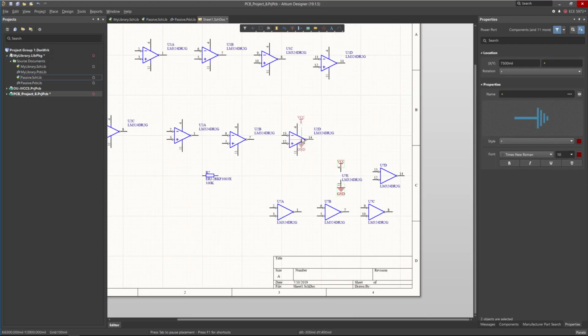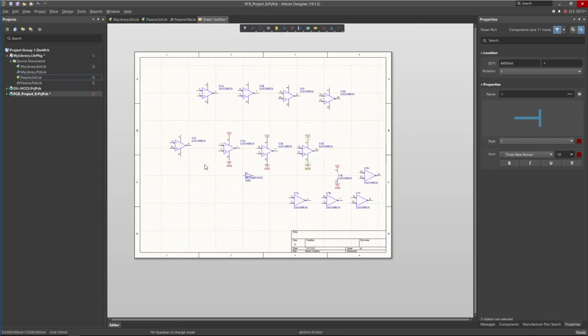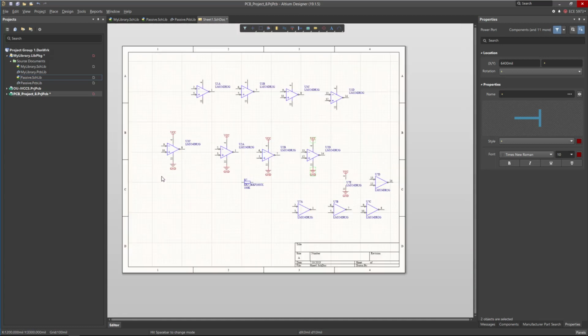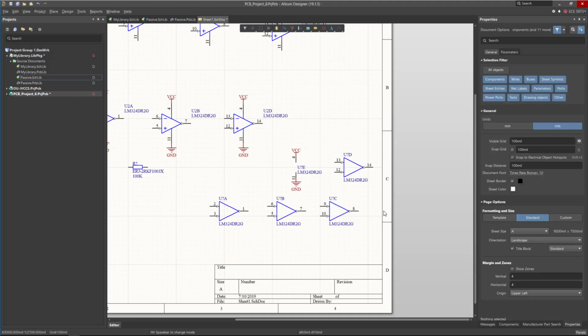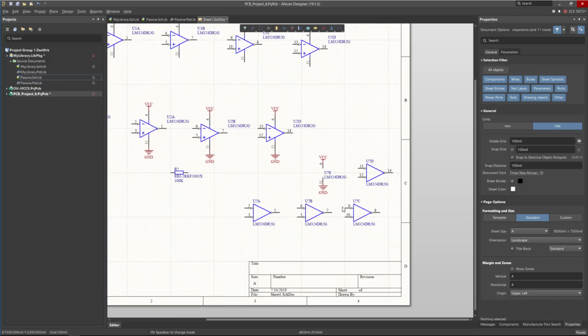Otherwise, I would have to do that for all these pins in here, for every single one, and these are just redundant pins. It makes no sense at all for me to do that. So this is how it should be done. This is much nicer, and this will not create an ERC error when you compile the project. Look how nice it is.